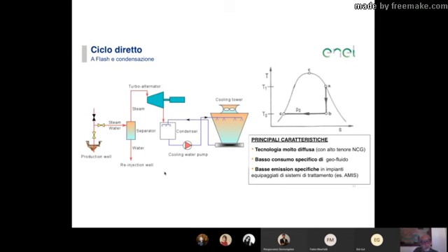What are the drawbacks of this kind of cycle? First of all, you would like to have from the production well as much steam as possible. So you actually like to produce steam down in your geothermal reservoir. And to do this, you simply decrease the pressure in the geothermal reservoir so that the pressure is below the boiling point of the water for that temperature.